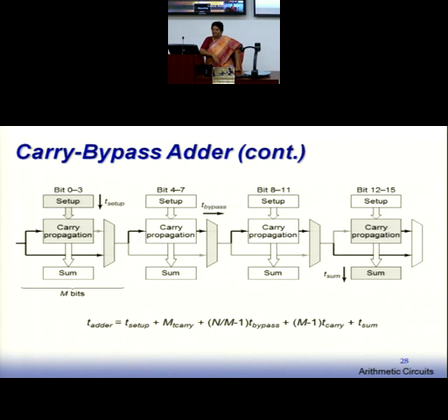Rather, it would be better to have a tapered kind of architecture. So you have increasing, coming to a certain value of the number of bits per block and then coming down. This is known as a variable skip pattern. And you can find out now the best way to size the blocks. 2 bits, or should it be 3 bits first, then 4 bit, then 6 bit?